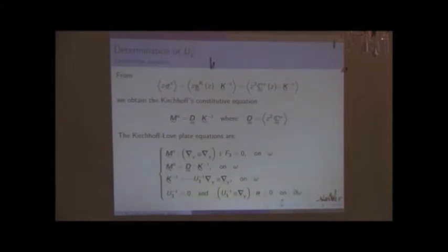And just for those who are more familiar with beam theory, if I compute z squared times E, E being the Young modulus, I will have 1 over 12 E. The 1 is because I have a non-dimensional problem, but if I were with physical variables, I would have T cubed over 12 times E. And you recognize the second moment of inertia.